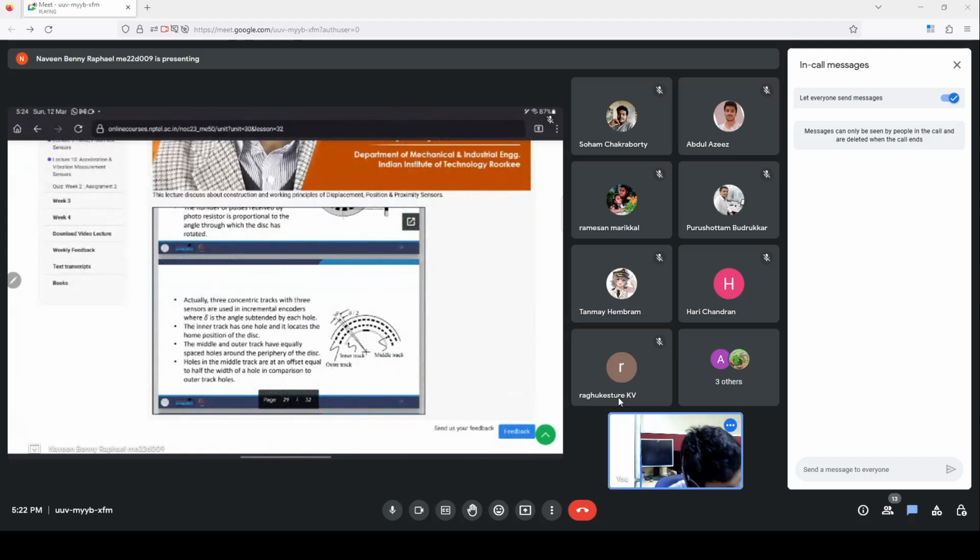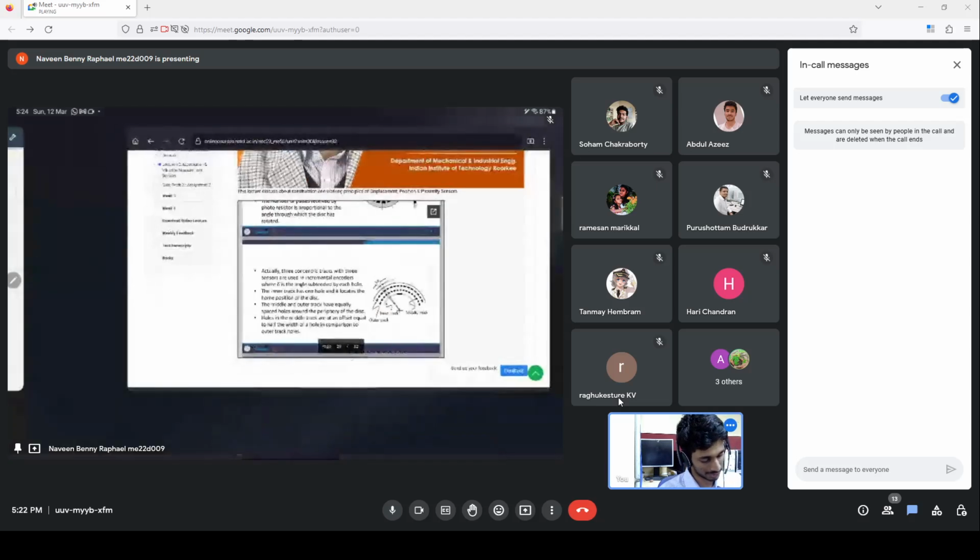Because of a slight change in the displacement, if light shines, depending on which ring gives us the output first, it is possible for us to say whether the wheel is spinning clockwise or anti-clockwise, and that will help us give the angular orientation. And the final ring is to give a reference point, to say that this is, let's say, the origin, or something of that sort.